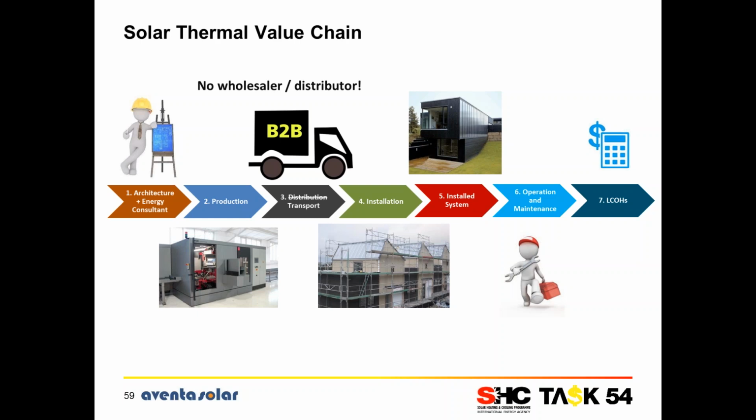The second part is related to point 4, that the solar products are lightweight, easy to handle at the building site, and no specific infrastructure or cranes, except for those which are already on the building site, are needed for the collector installation. So the collector installation is a part of the whole building process. It's also so that the collector has a standard width, which fits the standard building width in Norway. It's 60 centimeters, which is straightforward.